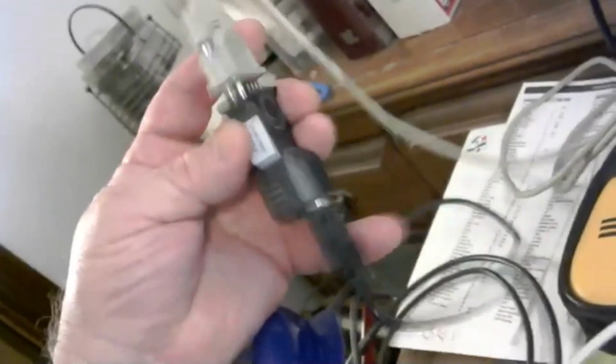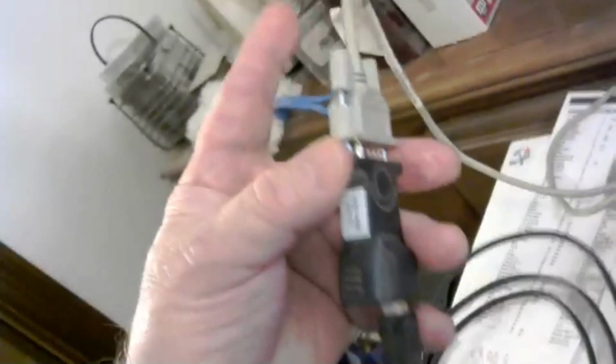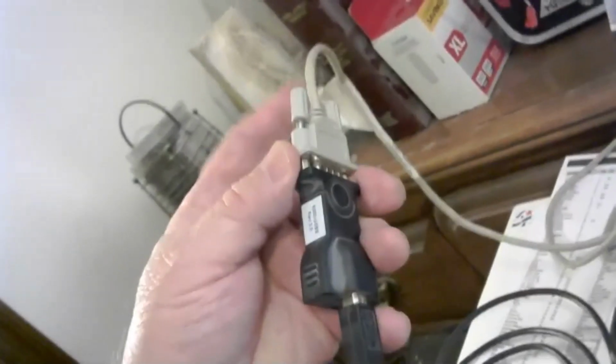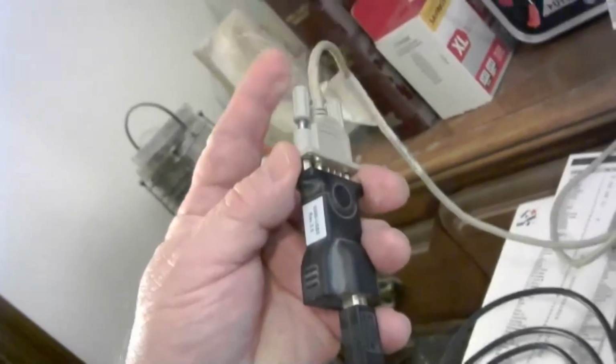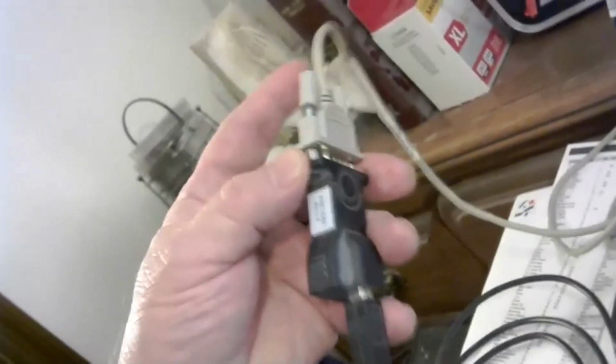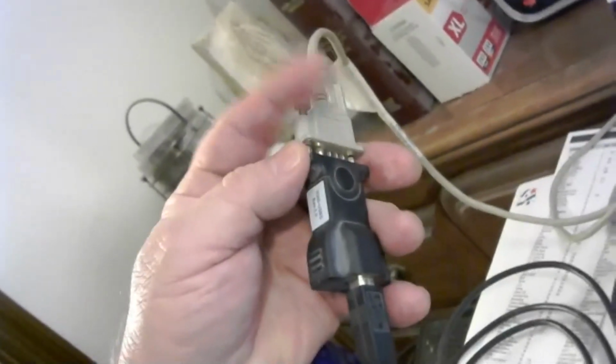So look, USB is really serial, but it's a universal serial bus. This up here, the 9-pin serial, is called RS-232 serial. That's one of the things you'll see when we have to go pick the driver here in a minute to go online with the PLC. The driver that you've got to use for this cable is an RS-232 type serial driver. So you're still going serial out of the laptop.